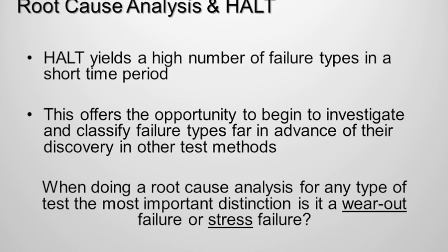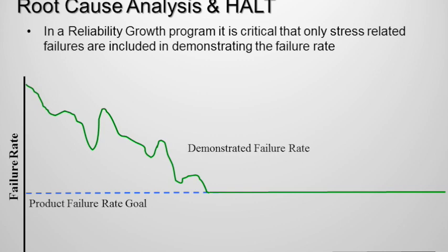How about HALT and root cause analysis? So HALT yields a high number of failure types in a very short period of time. This offers the opportunity to begin to investigate and classify failure types early. So when you're doing something like a root cause analysis for any type of test, the most important distinction is: is this a wear out failure mode or a stress failure mode? One of the most critical programs, I believe, is a reliability growth program, where if you are not able to clearly distinguish between a stress-related failure mode and a wear-out failure mode, your results can become very contaminated.